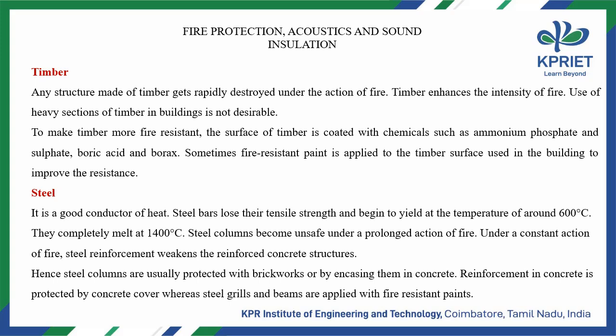Steel. It is a good conductor of heat. Steel bars lose their tensile strength and begin to yield at a temperature of around 600 degrees Celsius. They completely melt at 1400 degrees Celsius. Steel columns become unsafe under a prolonged action of fire. Under a constant action of fire, steel reinforcement weakens the reinforced concrete structures. Hence steel columns are usually protected with brickworks or by encasing them in concrete. Reinforcement in concrete is protected by concrete cover, whereas steel grills and beams are applied with fire-resistant paints.